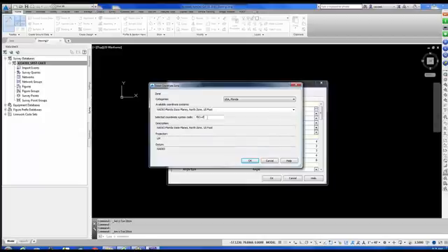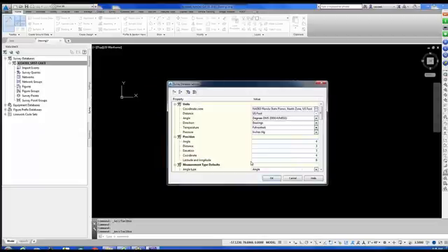Make sure that you put the letter F at the end. If you don't, you end up with meter. Now, anytime that you see a circle on the screen blinking like this, it's me hitting my control key to show you where my cursor is. So you see where it says meter? If I hit the letter F, see how it changes to US foot. Occasionally people don't type in everything and they wonder why things aren't coming in where they're supposed to be. All right, we're going to hit OK.